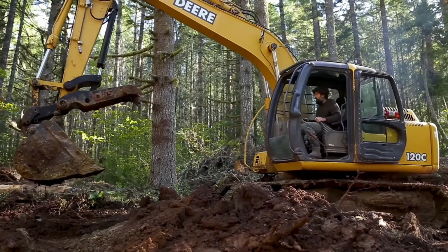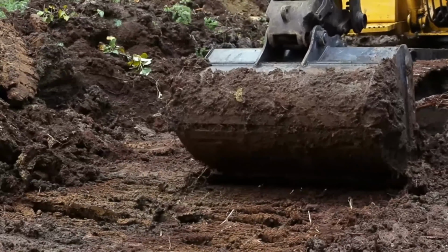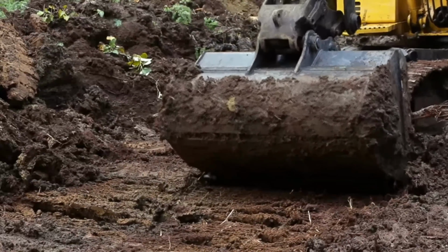So my process with construction is to start by clearing the topsoil of all organic material and debris and getting down to what feels like an adequate workable material for the main frame construction of the pond. This means that we're removing at least the organic and maybe the A horizon of soils. That typically just gets pushed downhill of the dam, and we'll use that later to skin the entire outside of the pond. The area that gets focused on next is the cutoff excavation zone of the dam itself.